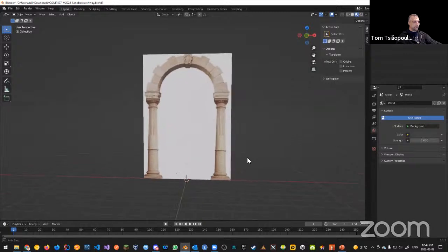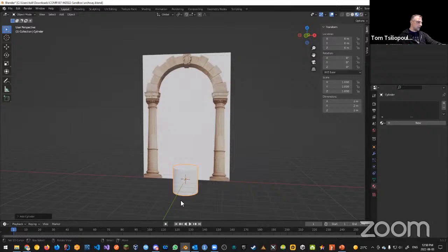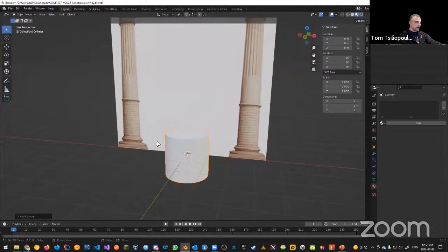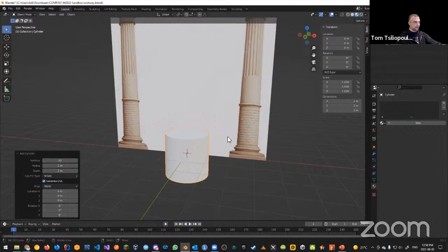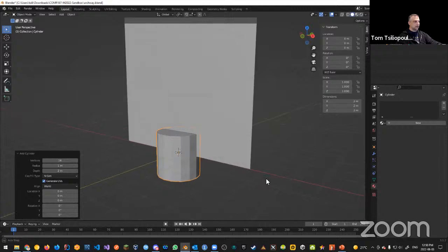And once we've deleted the cube, then we can add a new cylinder in. So add in a mesh, which is a cylinder. So we add that cylinder mesh in there. Now, one thing to note when we zoom in here and see the cylinder itself, be careful with the number of cuts again, right? The cylinder right now has 32 vertices. We want it to be more granular like this and lower poly. So we want to go to something like 16 vertices. And again, if I was going to go into a very dense mesh, this was kind of what it would look like.